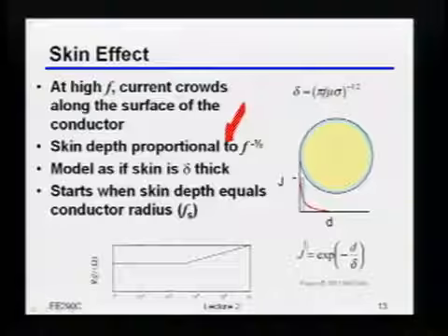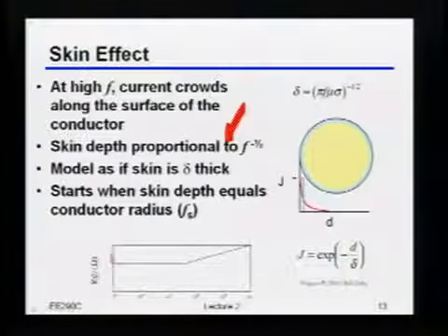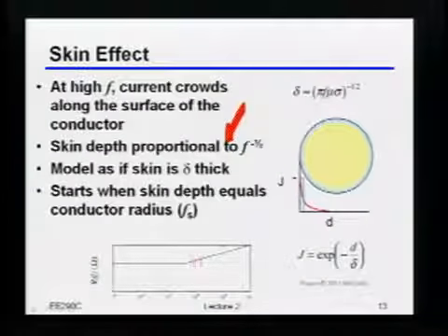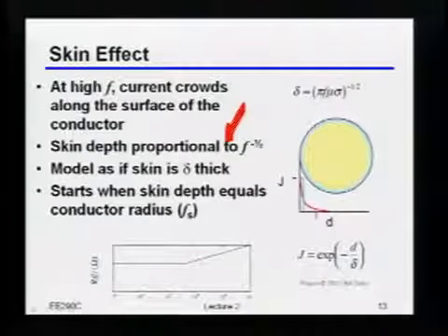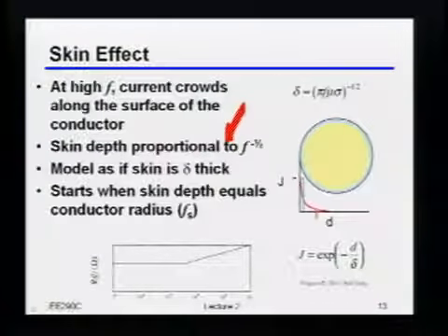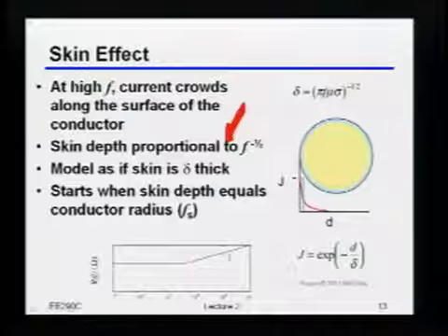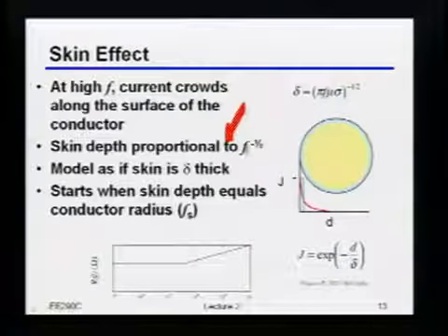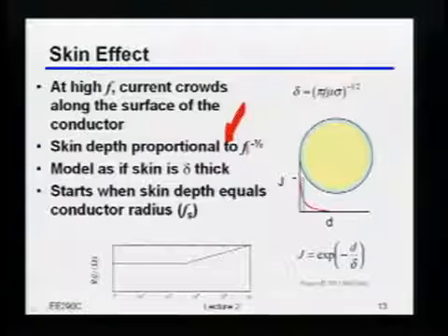And then basically what you'll see in 1 second is that, as you can imagine, actually you can see on the plot here, once this really starts coming into effect, then your resistance just starts going up very, very quickly, which means your loss also goes up very quickly. So in particular, what this basically says is that the loss is kind of related to the exponential of the square root of the frequency. Okay, and we'll see that again in 1 more second.